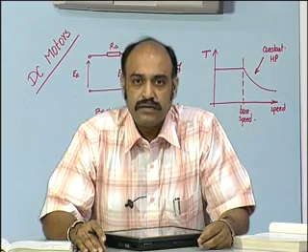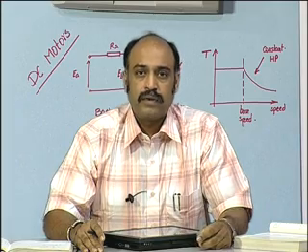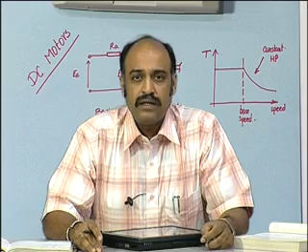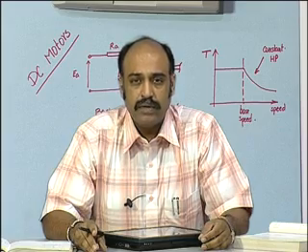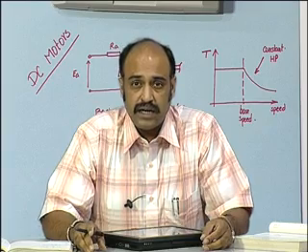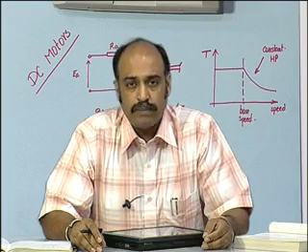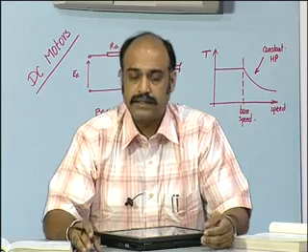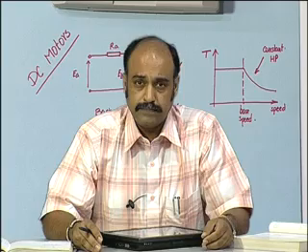In the last session, we had started our discussion about the DC motors. Principally, the DC motors and the DC generators belong to the same class, with the structure of the machine or the structure of the equipment being similar in both the cases. The structure of a DC generator can be used even for a DC motor, only that the flow of power is reversed. In the case of the DC generator, the power flows from the mechanical side to the electrical side, and in the case of the DC motor, the flow of the power is from the electrical to the mechanical side.